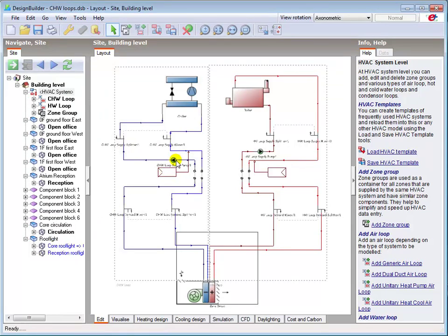The default chilled water supply subloop includes a single chiller, splitter and mixer, a circulating pump and a set point manager. The splitters and mixers here in the supply subloop provide the connections to enable you to add chillers. The demand subloop is automatically connected to the supply subloop and provides the splitter and mixer connections required to connect the loop to other system components such as air handling units and zone terminal units.